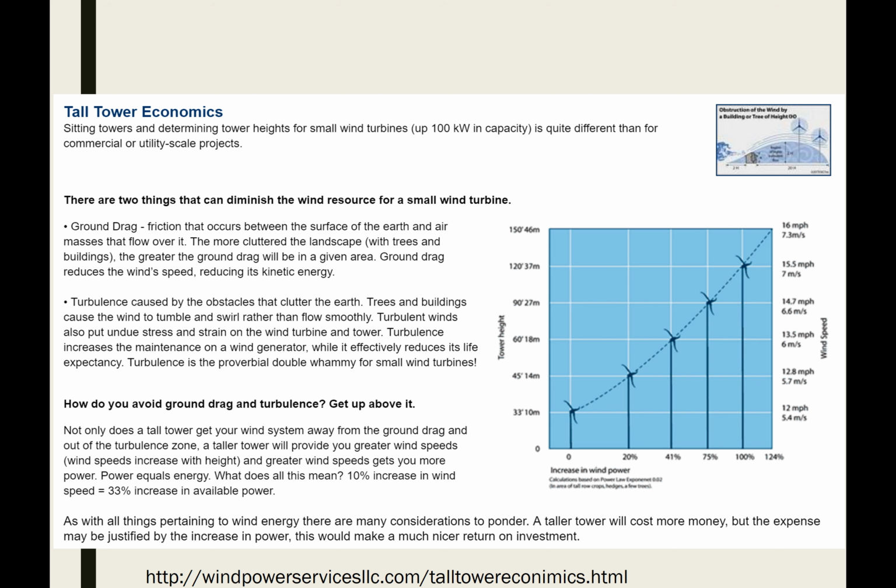But even if it were wind flowing over a perfectly flat field, the wind speed would still be higher up, because the ground itself, even with wind flowing exactly parallel to the ground, is going to cause a drag force that'll make the fluid flow more slowly toward the surface.